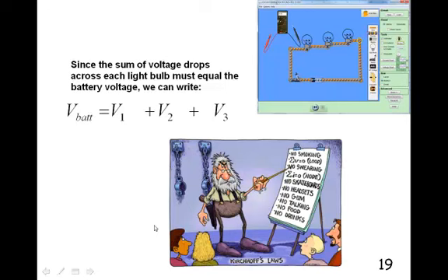All right. Well, the thing that we discovered in that little simulation is that the current, when these three elements are in series, and what defines what a series circuit is that the current through one element is the same as the current through this element. So if the current that goes through one thing is the same as the current that goes through the other one, they're in series. Or if we use the little bug model that we used with capacitors, if you're at this battery and you're this bug taking a trip, and if you go through one of the elements and the only way to get home is to go through this door and then through that door, then all those doors are in series.